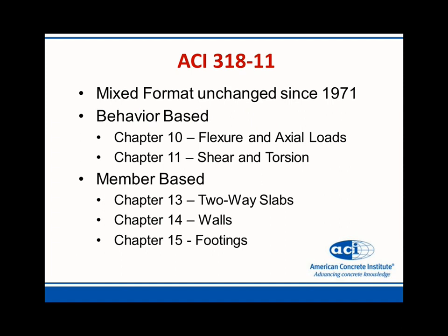It's a mixture of behavior-based requirements. For example, Chapter 10 addresses flexure and axial loads. Chapter 11 addresses shear and torsion. But there's also some member-based chapters. Chapter 13 exclusively addresses two-way slabs. Chapter 14 addresses walls. Chapter 15 addresses footings.